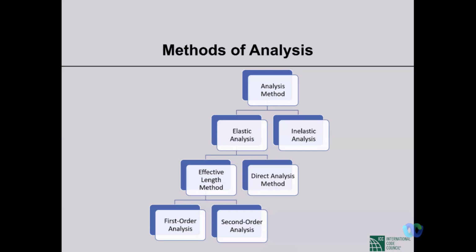But usually in the design office, we don't want to go for non-linear inelastic analysis because it is very time consuming. The modeling is difficult, and running the program takes a lot of time. So we want to avoid this too theoretical type of job in the design offices, and we always prefer elastic analysis.